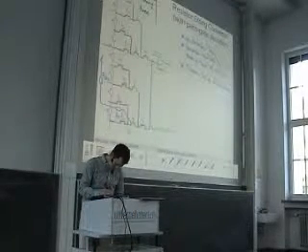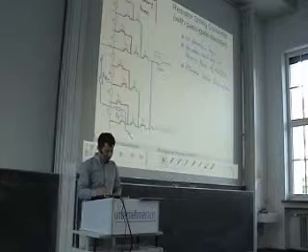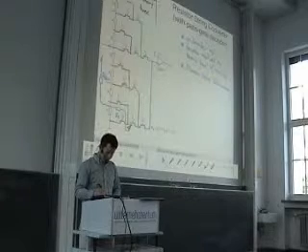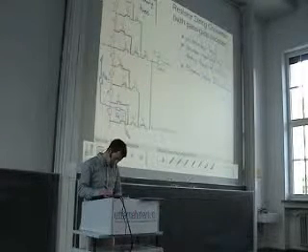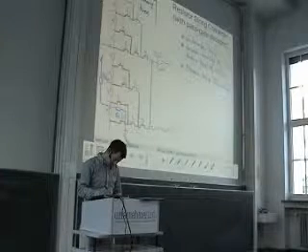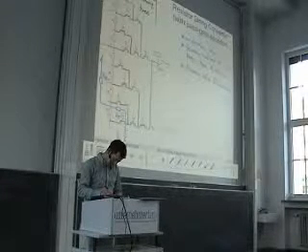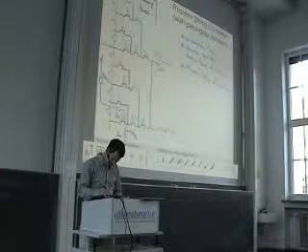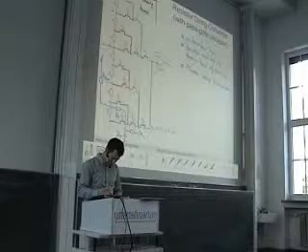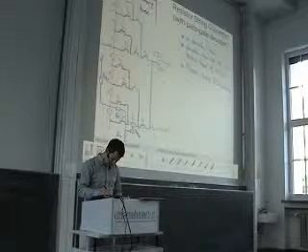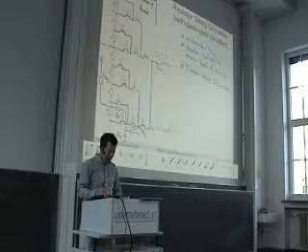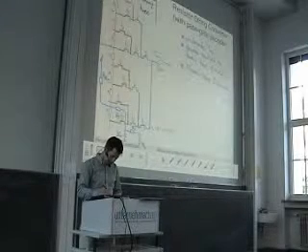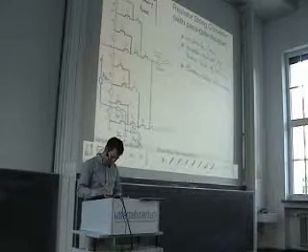Then we come to this node, and this node has 3 transistors connected. So effectively here 3 CT. Then we have the parasitic on resistance of another switch, an RT here. At this node we have again 3 transistors, so we can say here also 3 CT.